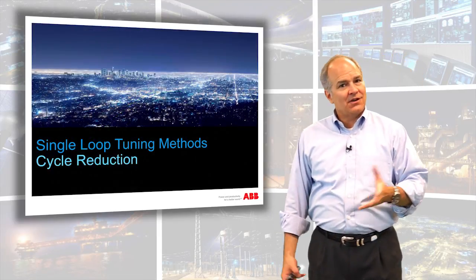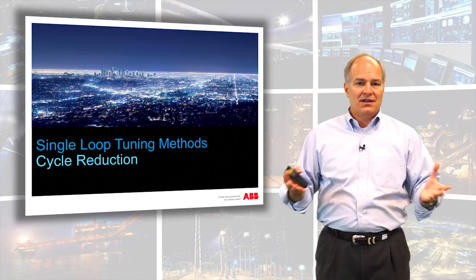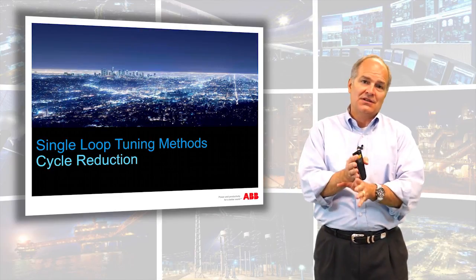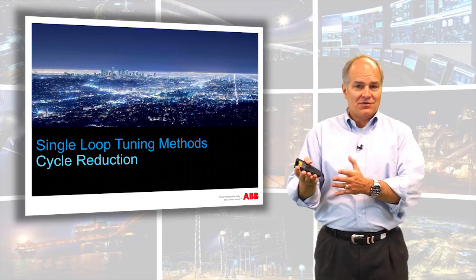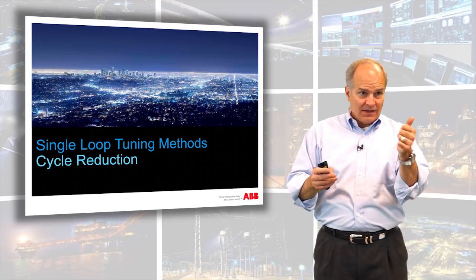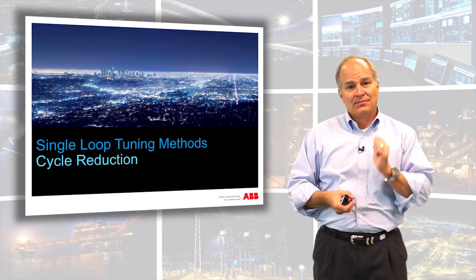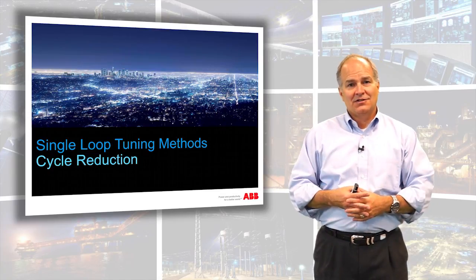So in this particular talk, we talked about dealing with cycles and oscillations and trying to identify that frequency that control can address. 2 pi times the closed loop time constant gives you a number that you can use to decide: if it's to the left of that, it's good. If it's to the right of that, it's going to pass through. That's dealing with cyclic disturbances.